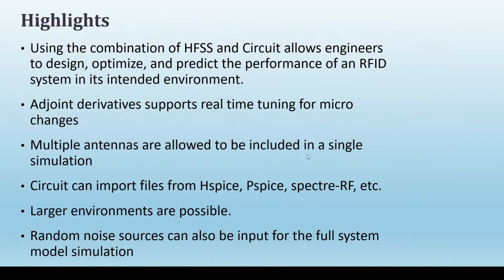Yep. Last but not least, I will highlight a few things to conclude our RFID system simulation today. First thing is, one of the most powerful things with the ANSYS tool is that we can combine HFSS and Circuit to design our full system, like a full antenna system.